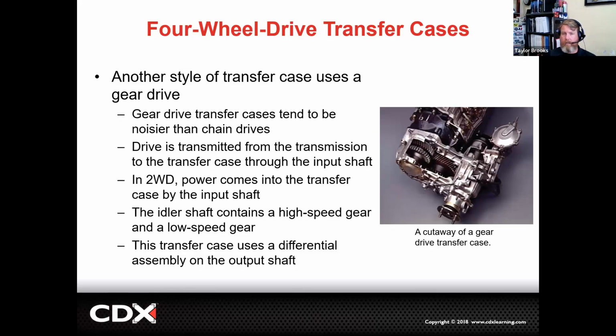Toyota Land Cruisers employ these, as well as Land Rovers, every version of actual off-road Land Rover, not the small front-wheel drive one that's effectively a Ford Focus, but the actual Land Rovers and Range Rovers and Discoveries, those are going to have this type of transfer case. We'll have a center differential, and any type of low range will be selected via those gears. It has the option to be two-wheel drive, or it has the option to be four-wheel drive.